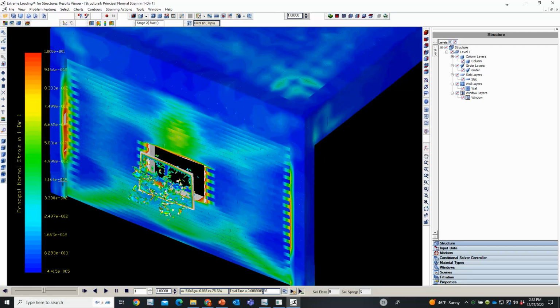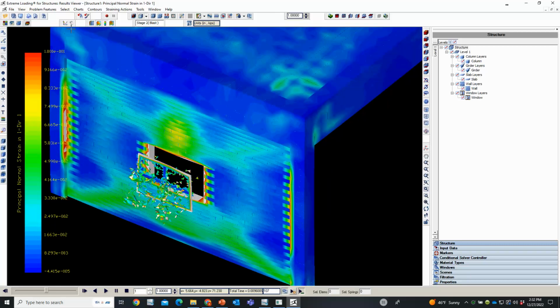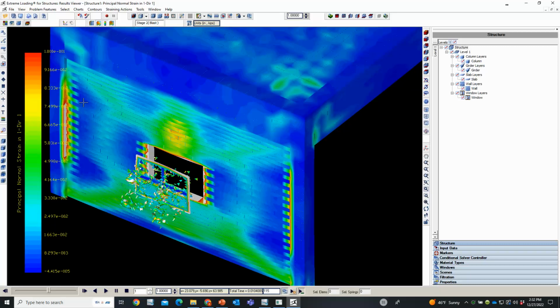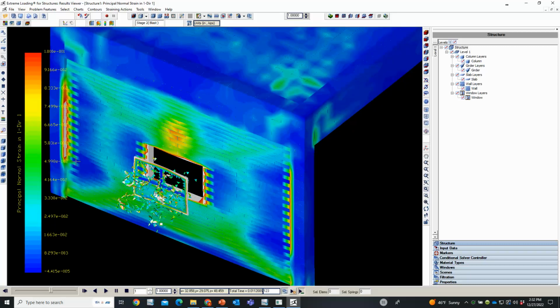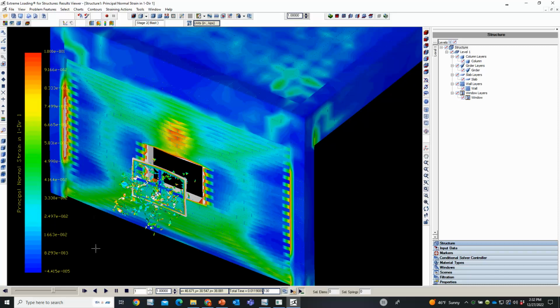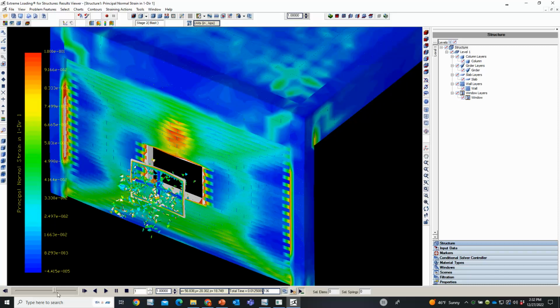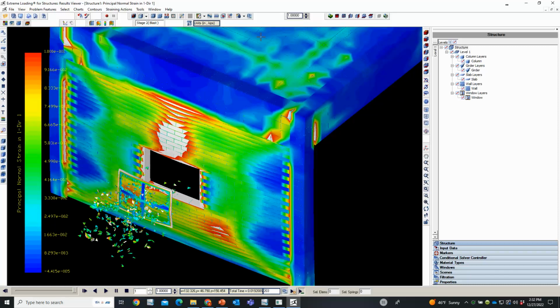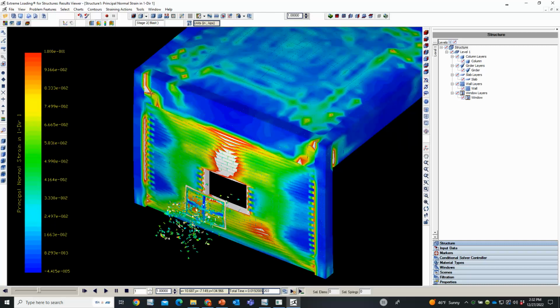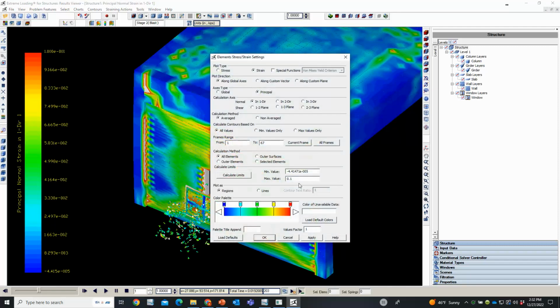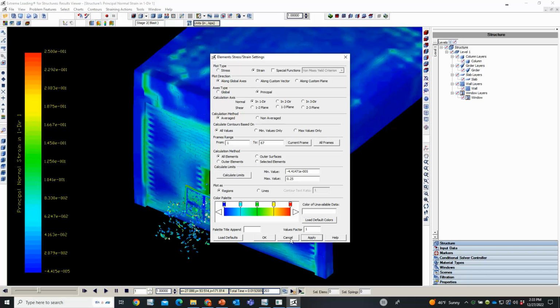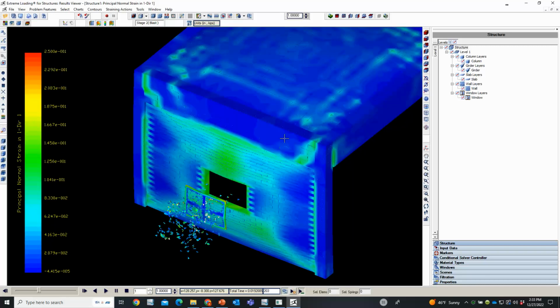As you can see here, there is cracking happening between the column and the wall, because as we said, this is mortar material by default. Let's bring the final frame so far. It's still solving. We can see here an initiation of a shear crack inside the beam. Perhaps we can view it or try to increase the value of the strain. We can see here shear cracking happen in the beam.